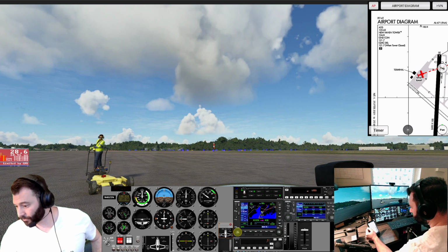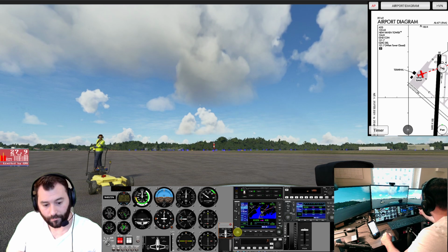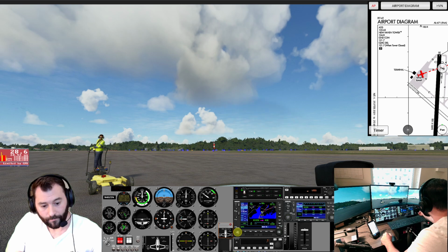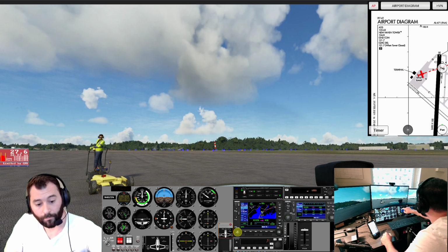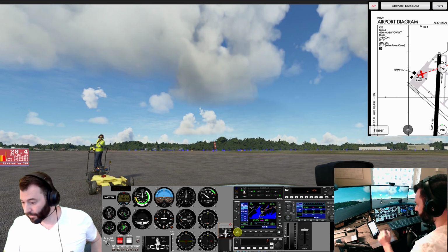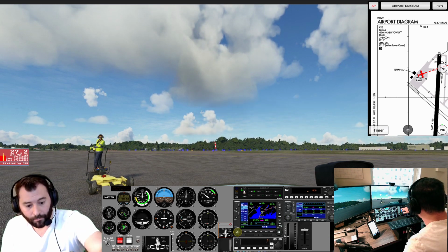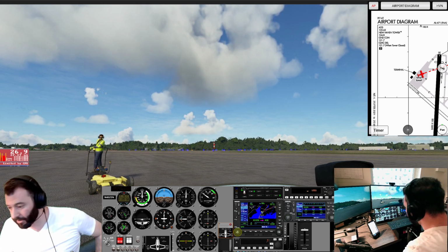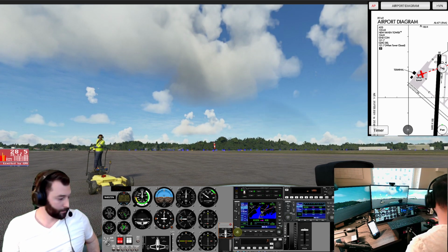Alright, we'll get rid of that. And we'll tune up the tower on airport information Kilo, 120.0, 124. Wind 285 at 7. Not entirely sure why that's still going. Sky condition, few clouds at 1,100 feet. So we'll just call that a simulatorism. Dew point 13. We'll put tower in there and be done with it. Okay, so we have tower up in the primary. Actually, we're going to tune up ground first. So we have 121.7, which is ground, in the primary, and we have 124.8 in the standby. So that's ground and tower.